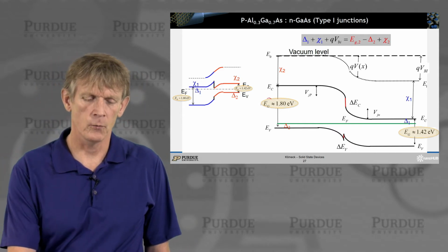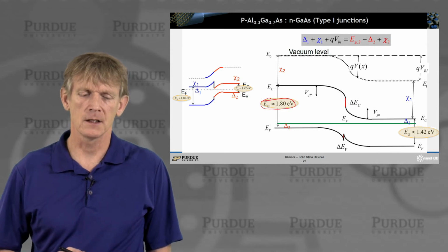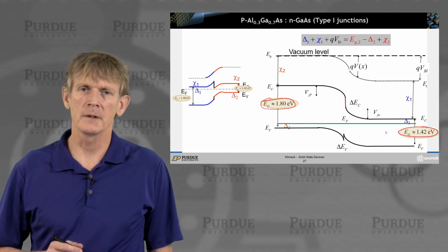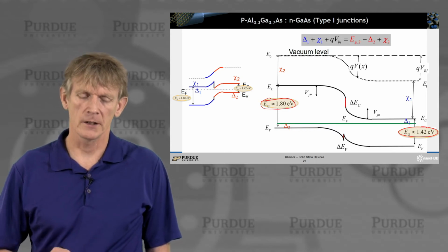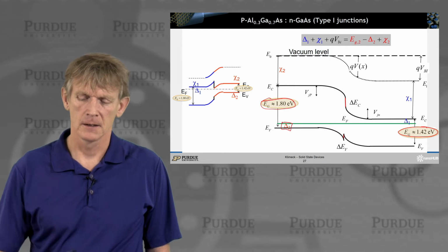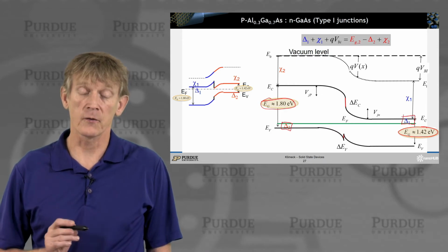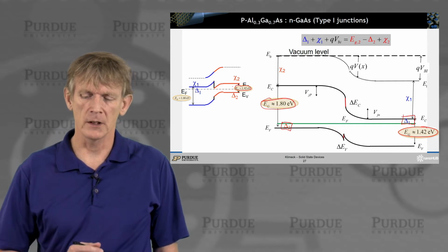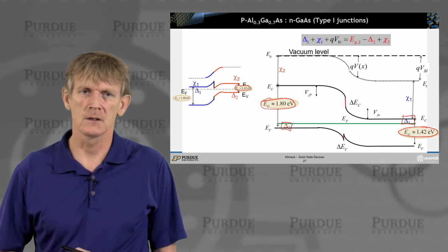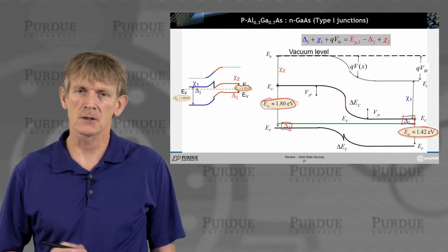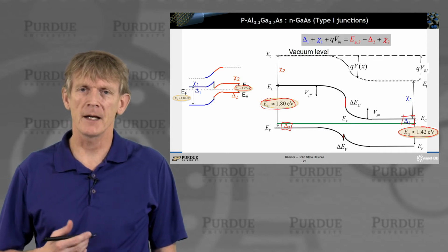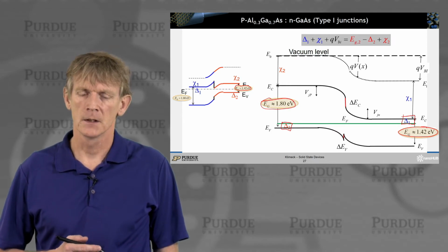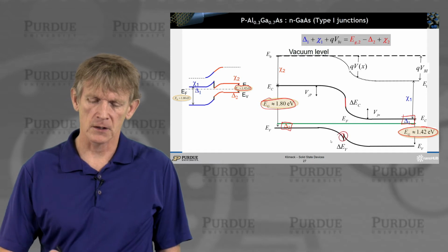Okay. Now, let me take the same heterostructure. So we keep the same 1.8 aluminum gallium arsenide here and the same gallium arsenide here, but let us dope it exactly opposite. So where you have P doping here and N doping on the right. So it's flipped from what we had before, right? The material is the same, but now we basically flipped the doping type. And the heterostructure looks quite different because the band bending on this heterostructure is very different. You do have a heterostructure offset here,